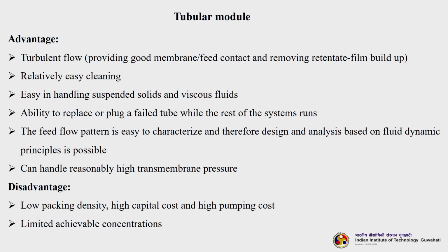That means the solute concentration developing on the membrane surface will be lesser if there is turbulent flow. Also, cleaning is very easy in tubular membranes, they are easy in handling suspended solids and viscous fluids, and there is the ability to replace or plug a failed tube while the rest of the system runs.